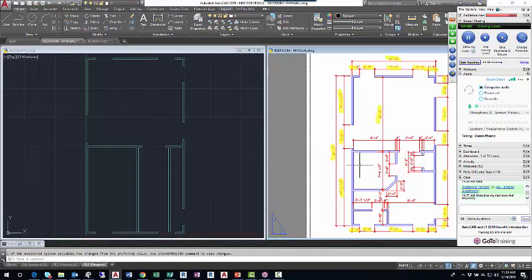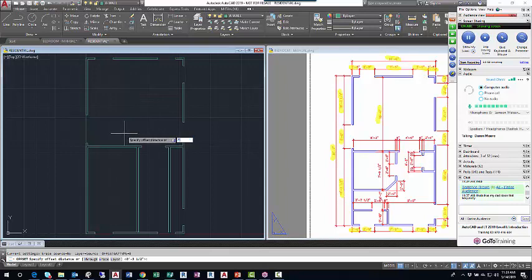I'm going to offset the bottom or the inside line. I'll highlight it here. I'm going to offset that line 7 feet 9.5 inches down the screen. So offset 7 feet 9.5, enter. Coming up from the bottom, I highlight that line, left click it, move down, left click.